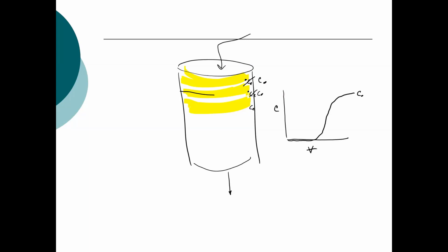So what I've done here is essentially gone from this completely mixed system to a plug flow system. So I can think of each one of these adsorption zones as being a CSTR, but having a sequence of CSTRs down the column. Okay. So that's in next week's processing. I'll look at columns and how they operate. But today we focused on batch and CSTRs.